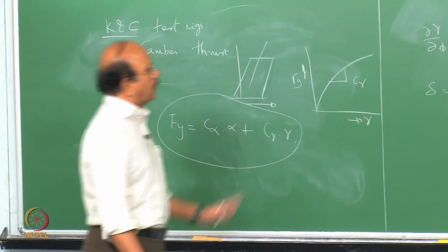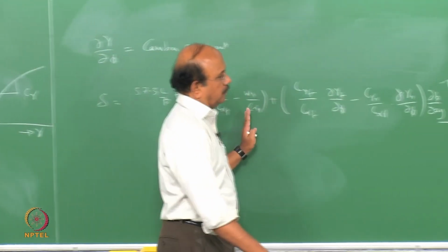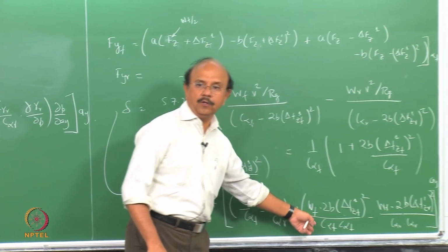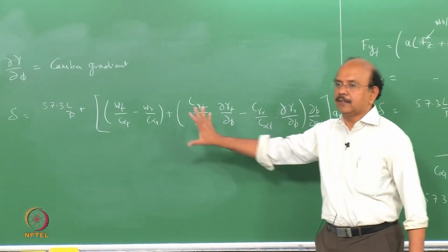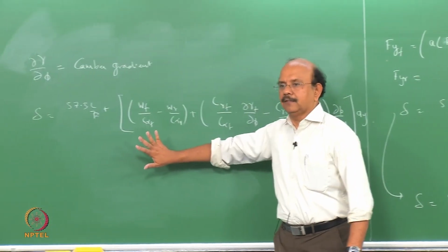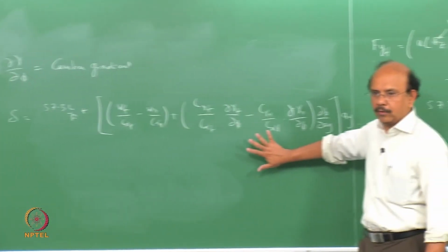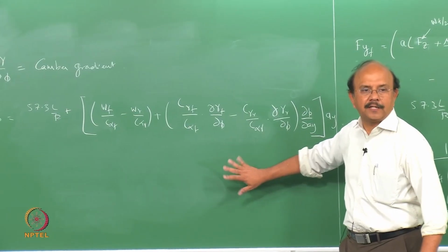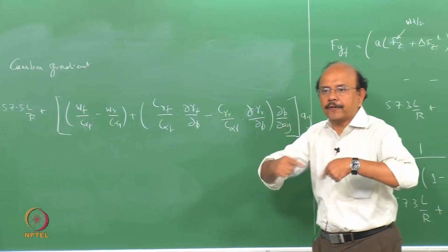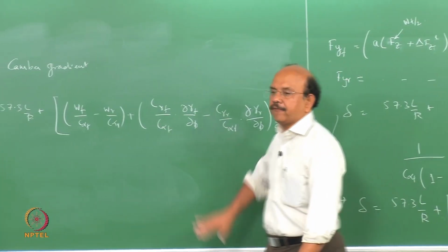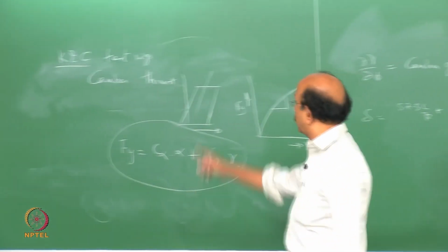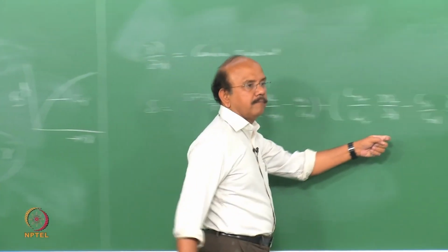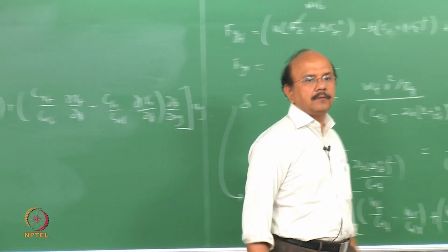Okay, so here we have not included this roll term. If I have to take into account the roll, then I will introduce that as well. Here we are only looking at the effect due to camber alone. So when you want to have a complete understeer gradient, then you have to add the effect of each one of them. So this is the effect due to camber change. So we have roll steer, and now we have the effect due to camber.